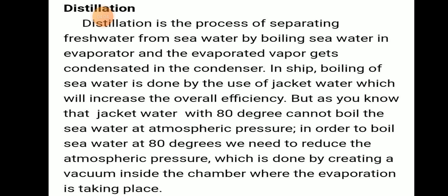In the ship, boiling of seawater is done by using jacket water, which increases the overall efficiency. You know that jacket water is at a temperature of about 80 degrees Celsius, and with 80 degrees Celsius we cannot boil seawater at atmospheric pressure. So in order to boil this seawater at 80 degrees Celsius, we need to reduce the pressure by producing vacuum inside the chamber where the evaporation is taking place.